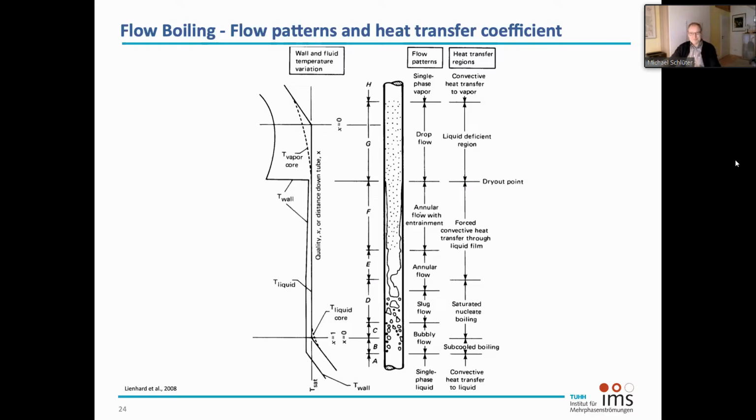Okay, so take this into account and be careful not to come to the situation, to this dry out point. You always need to have enough water in your cooling system to be sure that all the heat can be transferred.